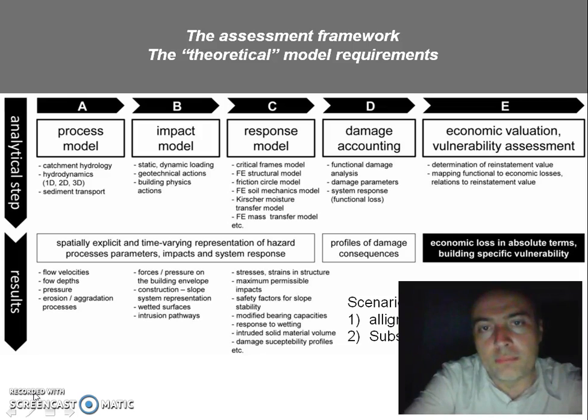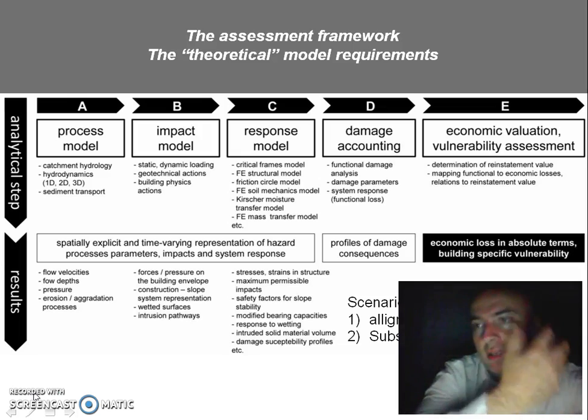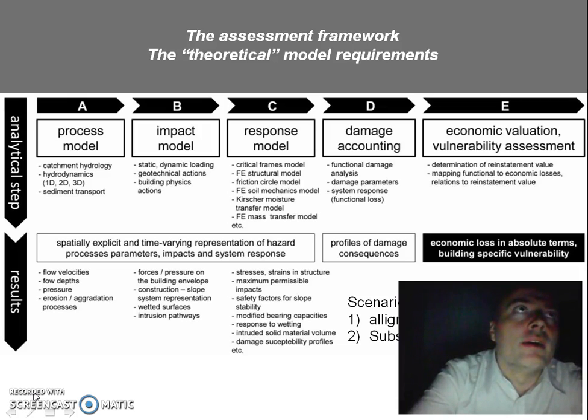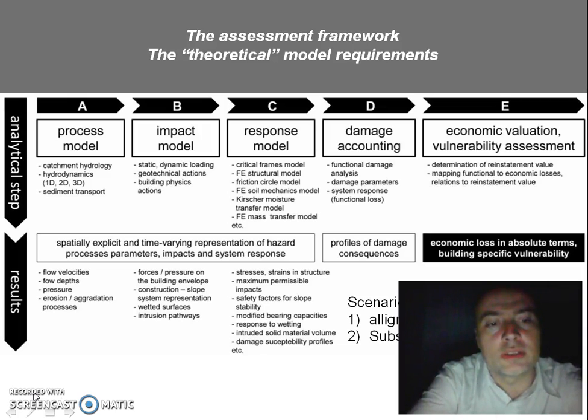Just imagine that people might be caught within a building due to solid material intrusion, and this might also be the cause of fatalities. I experienced it in an event documentation in South Tyrol in 2012, where in principle certain buildings exposed to debris flow resisted the impact from a mechanical perspective, but due to inconvenient opening locations, solid material easily intruded into the building, and due to this phenomenon, several fatalities had to be registered.